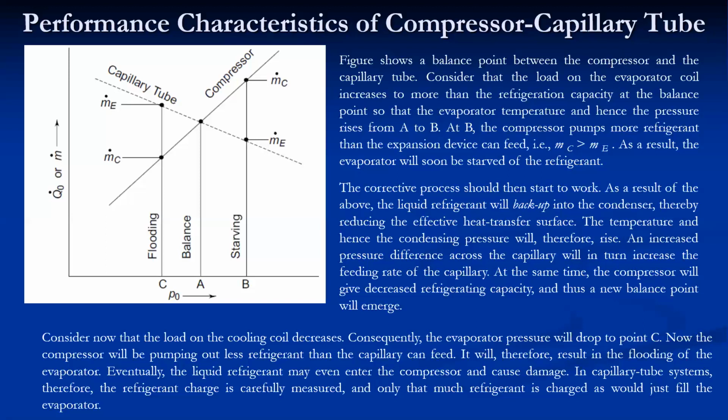So an adequate quantity of refrigerant should be charged in the compressor capillary unit to avoid compressor damage, because whenever a capillary tube is used, the compressor is generally a hermetically sealed compressor. So there is a possibility of flooding, where liquid may enter the compressor if the load decreases. But this is also a temporary situation.